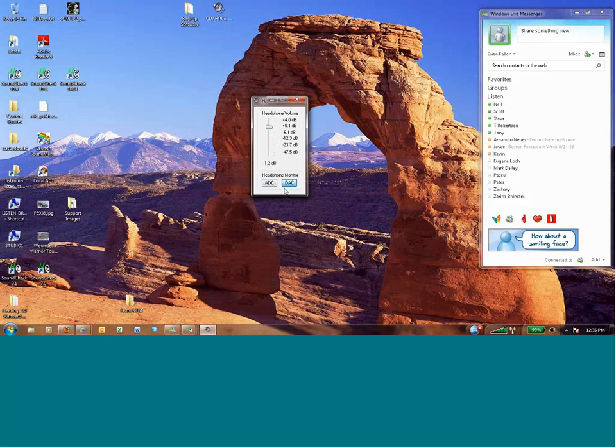So we have the A to D and the D to A. If we choose to monitor the A to D, what we'll be listening to is the microphone inputs. So if you wanted to monitor your signals during the test and just listen on the headphones. If you choose the D to A, you'll be monitoring the output, the stimulus. So in that case, this is how we would set it up to actually test headphones. We would want our stimulus to be routed to the headphones. So just a simple little utility to go and configure that jack.